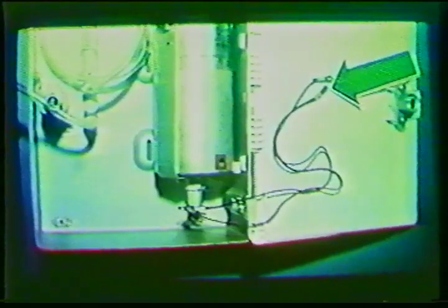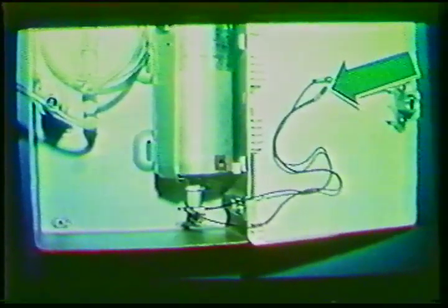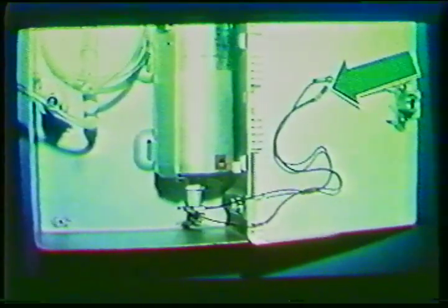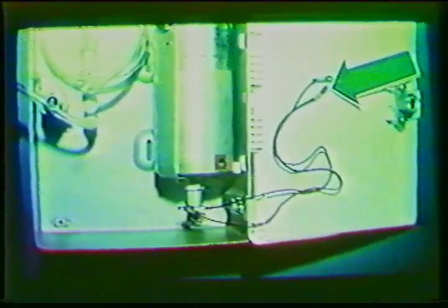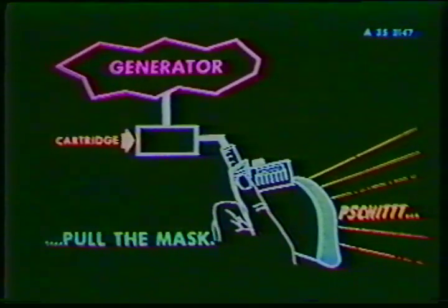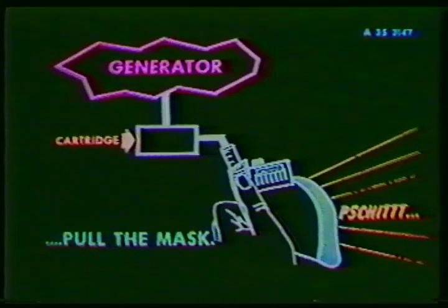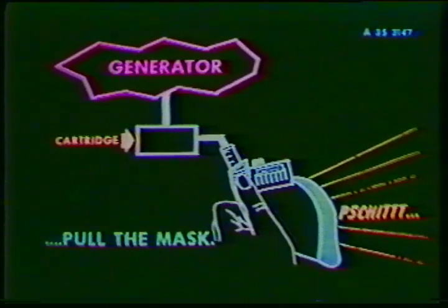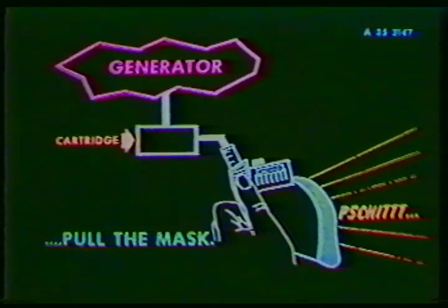Each unit contains a chemical generator and either 2 or 3 oronasal masks depending on the location. The generator is activated when a passenger pulls the mask down to his face. Once activated, it cannot be stopped and will last for approximately 15 minutes. A portion of the units containing 3 masks have an additional generator and outlet for first aid purposes.